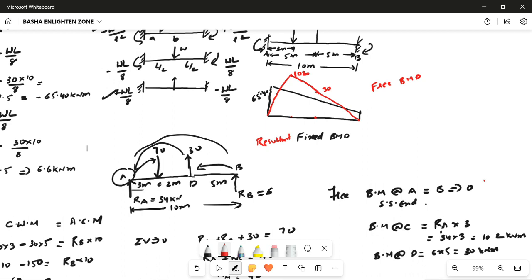So this is the way you have to draw the bending moment diagrams. If you want net calculations, for example, how to find the net moment? As I already told you, you have to find the ordinate up to here and here in this line. We solved many examples on how to interpolate this, by dividing it like a rectangle and a triangle.